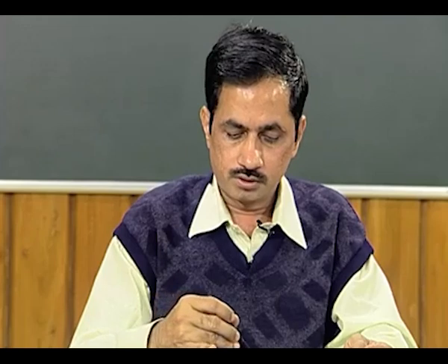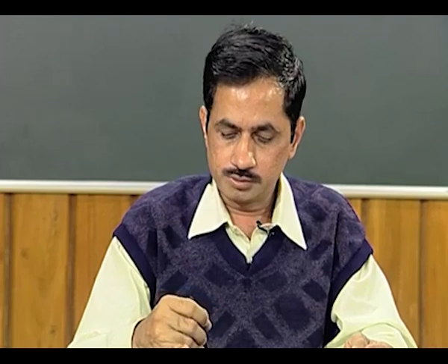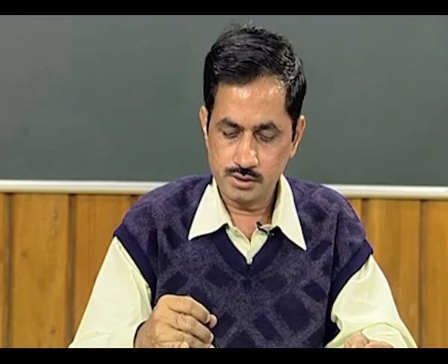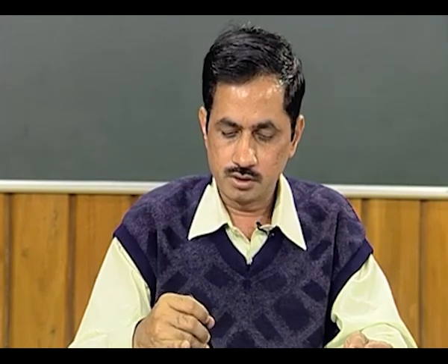So, we want the whirl frequency at one particular RPM, and also we can calculate the critical speed, because the whirl frequency is changing with speed and we need to track at what speed these frequencies are equal, and that is nothing but the critical speed.